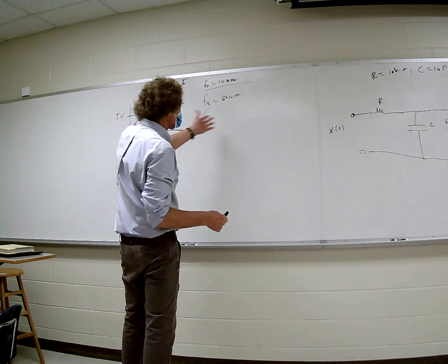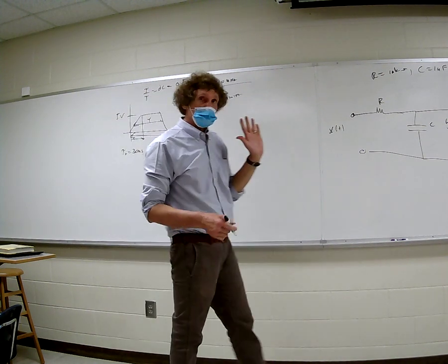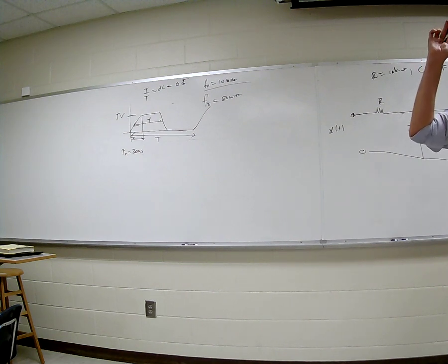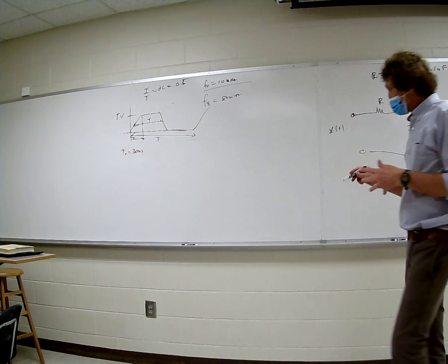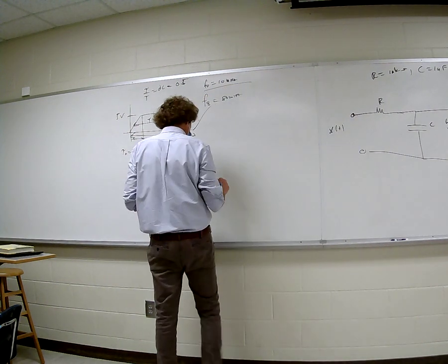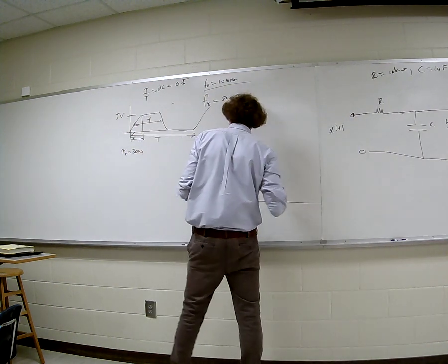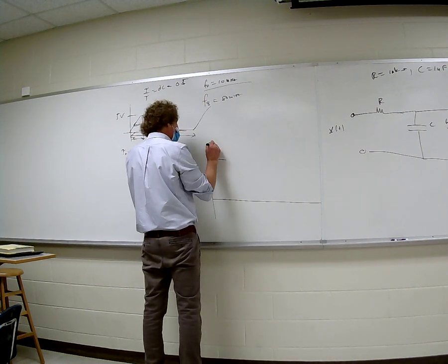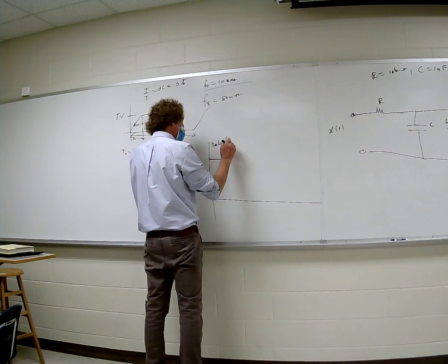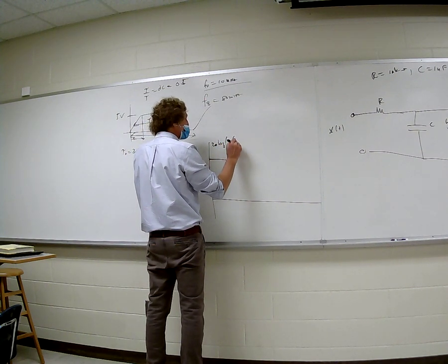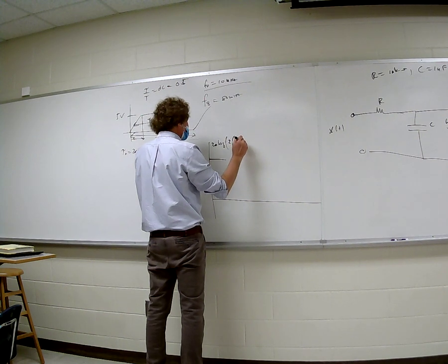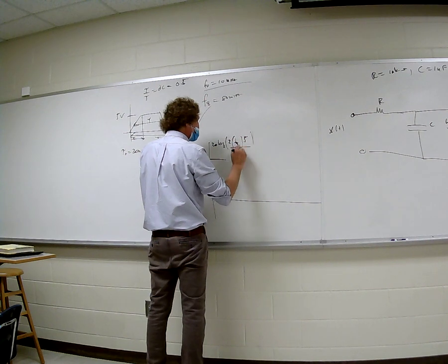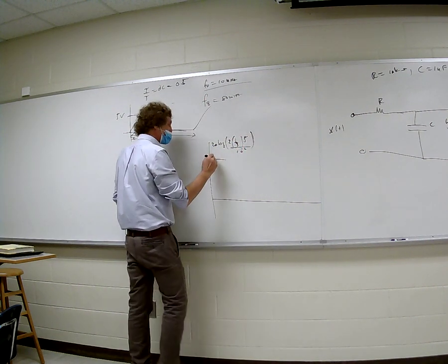First, we take a look at this waveform, and we draw it in terms of frequency versus 20 log of the magnitude of C1 times all that stuff. But one thing we do know is we'll have this curve no matter what. For any type of rise time, fall time, given duration, we're going to start off with a value of 20 times the log of 2 times the duty cycle, which is 1/2, times the magnitude of A, which is 5, divided by 10 to the minus 6. So that's where we start right here.